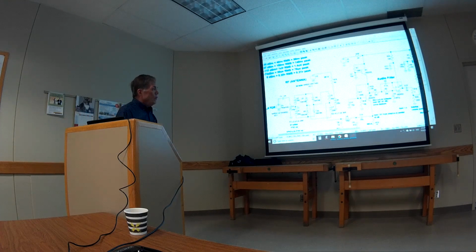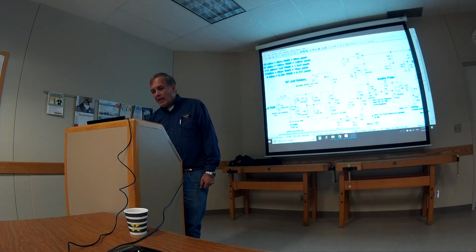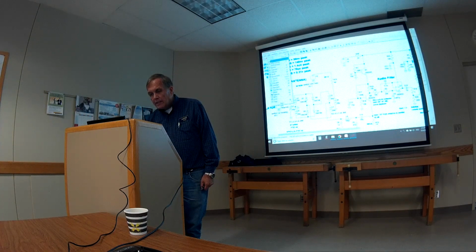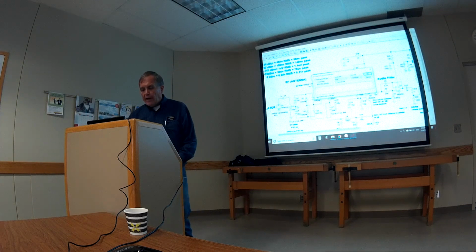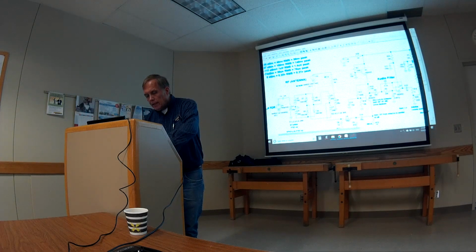Now, how do you tell that there's a transformer instead of 3 independent inductors? Well, that's a little trick. You see that K1 thing here? K1, L3, L4, L5, 0.999. Well, that's a SPICE directive again. You go up in the upper left-hand corner, you say Edit, and then instead of Text, you say SPICE Directive. And that allows you to put in values like that. I'm going to click on the one I have here.